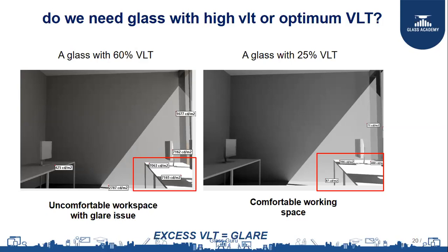So you will have to do an analysis and see what is the right amount of lux level and choose the products accordingly. Some software you have for analysis, we have Radiance, which gives you some insights into how much will be the lux level at different points. But to use Radiance, you will need a modeling software like Ecotect or SketchUp, which will give you an idea of how the geometry is, how the floor area is, how much glass is there, and if I use different VLT, how much will be the light entering inside.